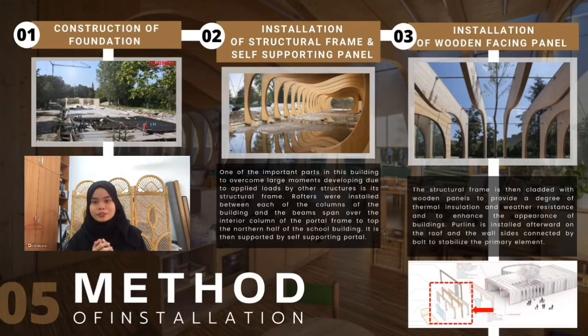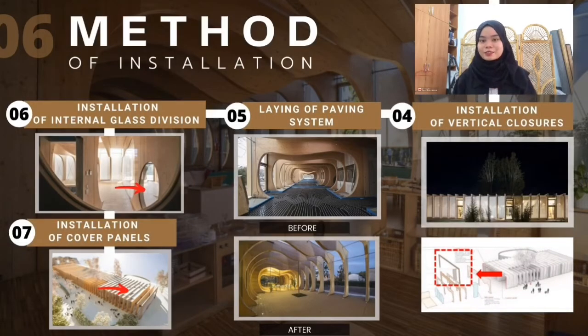and weather resistance, and to enhance the appearance of the building. Purlins are installed afterward on the roof and the wall sides, connected by bolts to stabilize the primary element. In addition, to provide thermal and acoustic insulation, the opaque vertical walls on the short sides and on the back, also known as vertical closures, are installed to isolate the enclosed space from the external environment. The transparent vertical closures are meant to allow natural lighting to pass through the building.